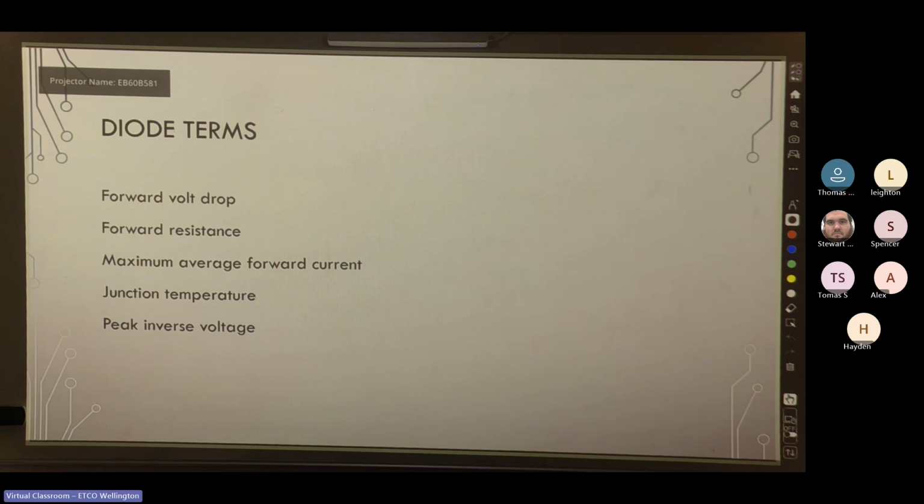Forward resistance, so we can use an ohm meter. It has a fairly low test current and will not be able to bias the diode to properly measure its internal resistance. Therefore, it will read quite high, between 100 to 1,000 ohms. If it's above 1 kilo ohm, that indicates a faulty diode. When forward biased, a diode's resistance becomes very low, typically less than an ohm, maximum average. I'll show you some diodes in a little bit after we get through the slides, and how to test them.